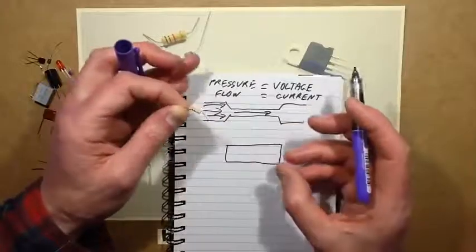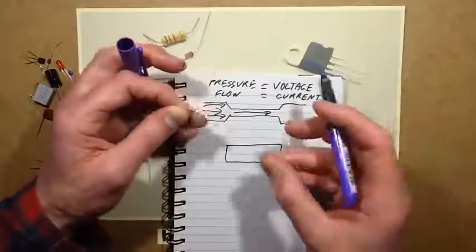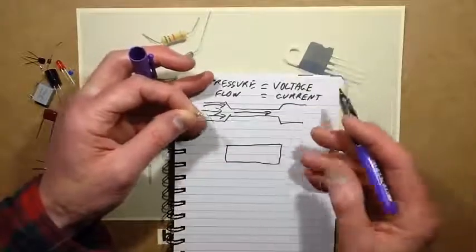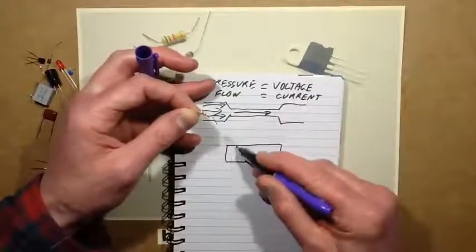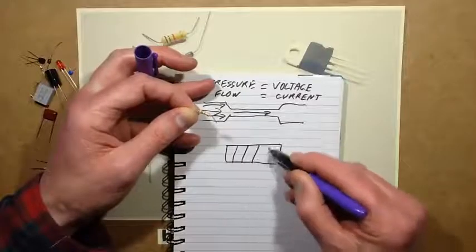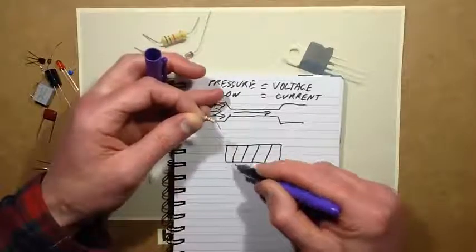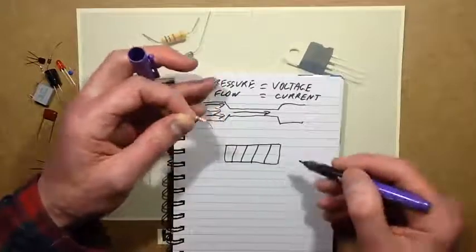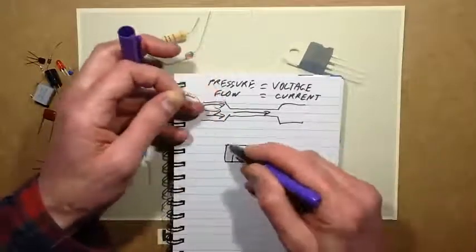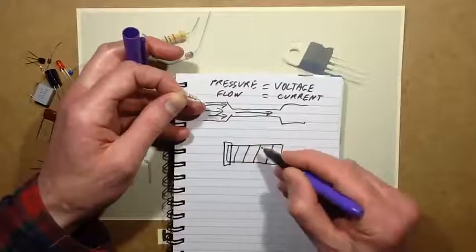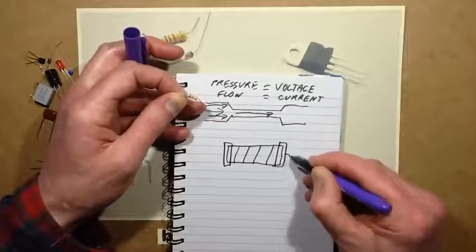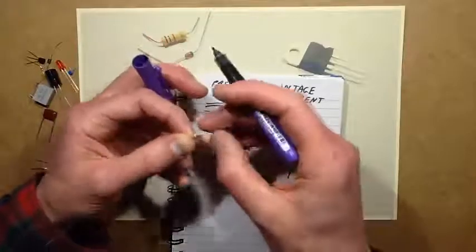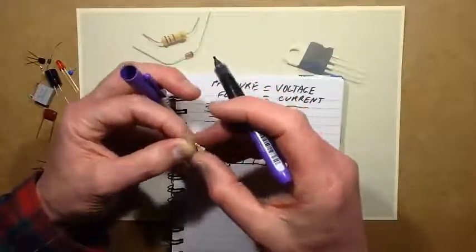And the thicker the carbon coating on it and the type of the composition they're putting on it, the more conductive it will be. But then they can fine tune that. They actually cut a spiral around it, and that creates a long thin path of the carbon, and that increases the value of the resistance. And once they've done that, they put a metal cap in the end with the leads coming off, and they dip it in a sort of, I suppose it's a lacquer really.